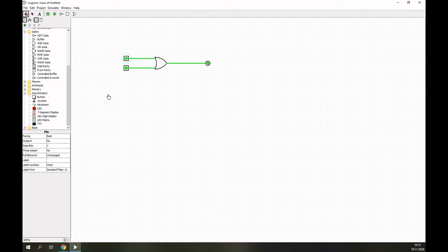And now remember what we did. So we replace it with an AND gate. So we set an AND gate. Also set the inputs to 2. We have another output so that we see the result. We connect the output to the AND, but we should not miss that we have now a NOT here.